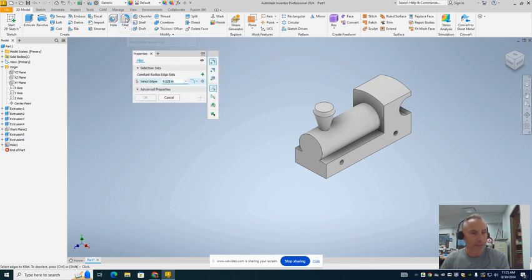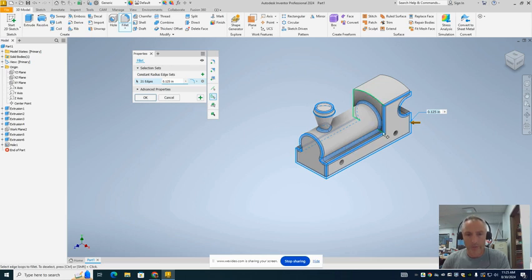So we'll click fillet, and we'll use a feature called loop, which is right here, because we don't necessarily want to select every edge, but we want to get almost every edge, and I'll show you that. So by choosing loop, as I pan around, it's going to give me entire loops of edges that I can select, and it saves me a little time. You are going to go select every edge on the train body with the exception of the holes. We do not want to fill up the holes because we're going to be attaching wheels and pegs to them, and by having them filleted would make it more difficult.